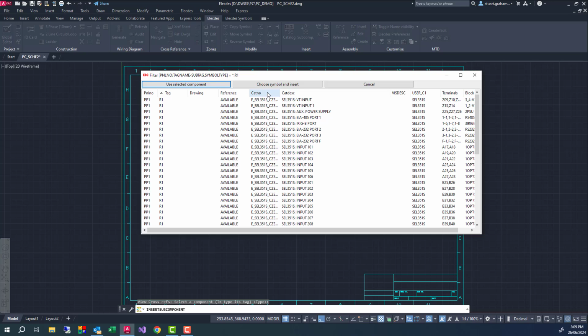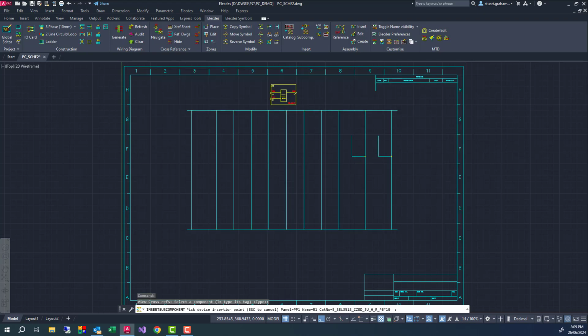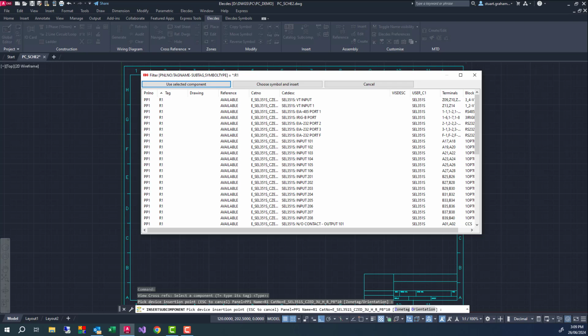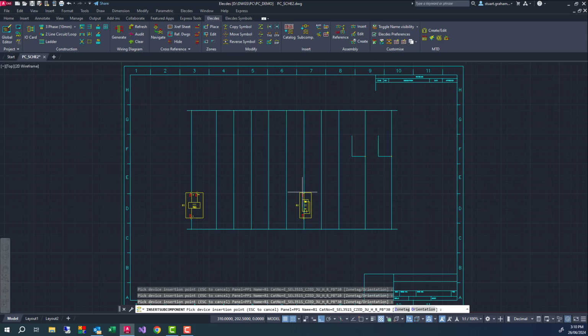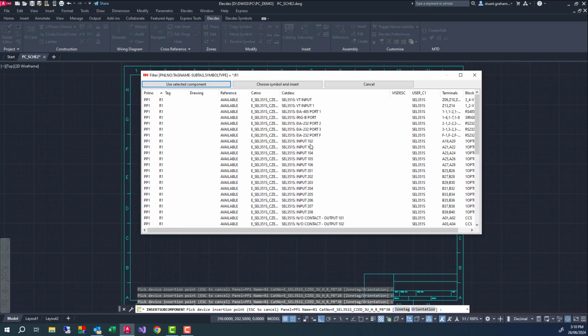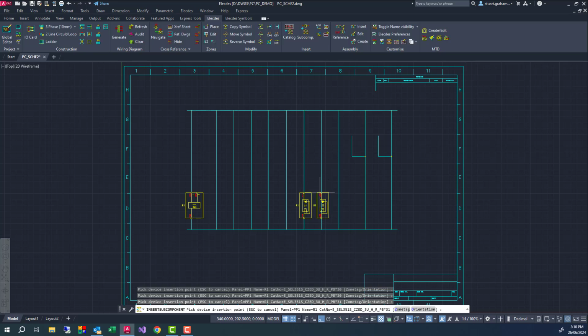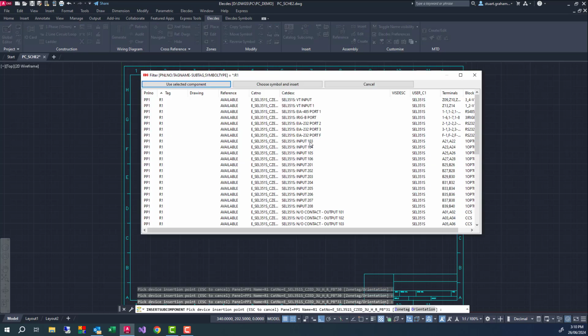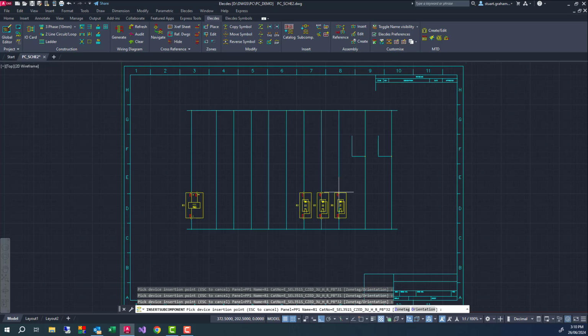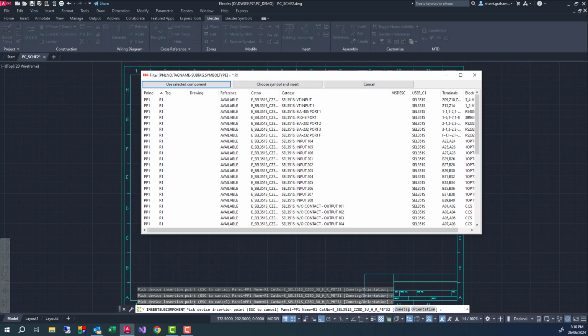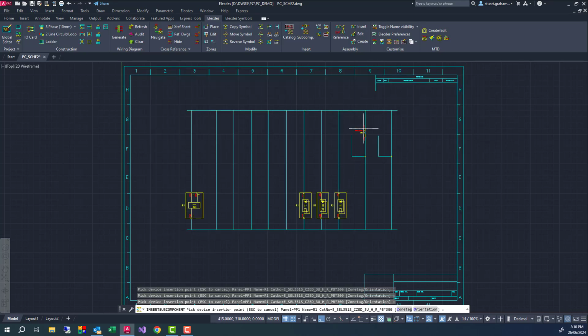I will firstly place the relay's auxiliary power supply onto my ladder. Now I will insert 3 opto inputs from the relay. As the symbols are inserted, they become unavailable for further insertion. This ensures no duplications occur. The terminals and ratings, such as input status or output function, are managed, saving a significant amount of production time and rework. Next, I will insert 2 contact outputs on the ladder.